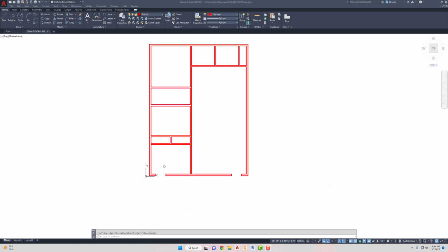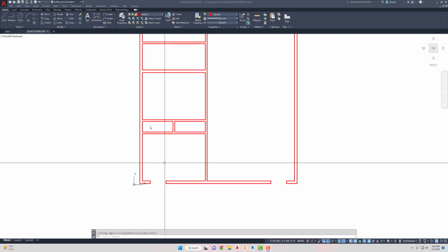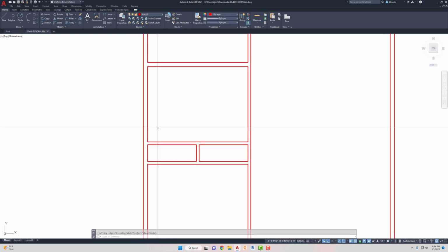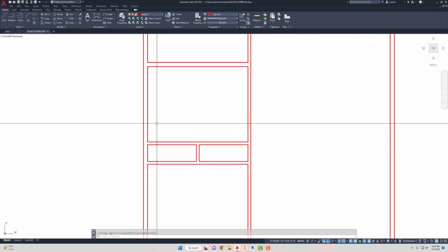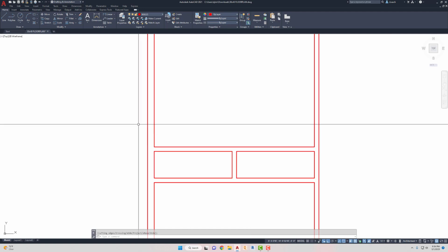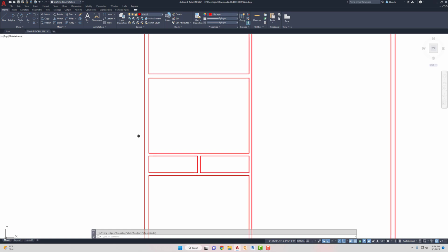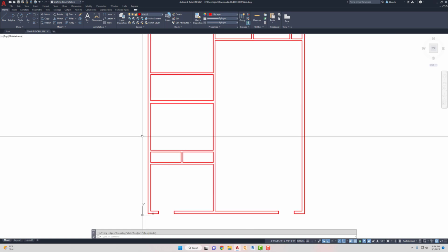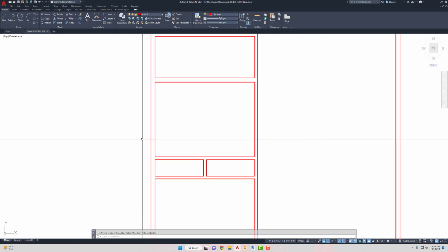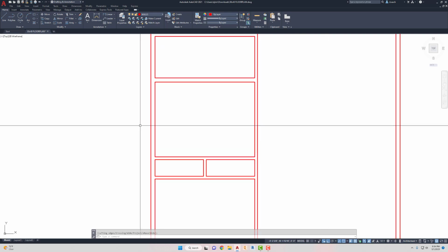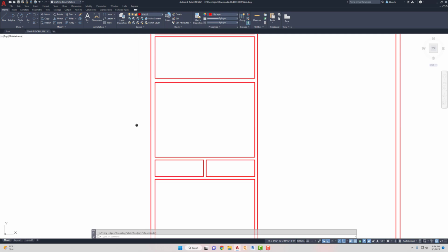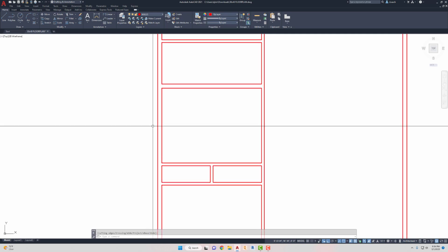All right, so let's go counterclockwise. There's a bedroom window over here. In the bedroom, you always want to have an openable window that's wide enough that you can get out in case of a fire. So just check your codes for what size exactly it needs to be. I don't want to tell you and get you in trouble. Like, oh, Mr. Leach, you told me that was a window and it was not big enough. But anyway, check your codes.